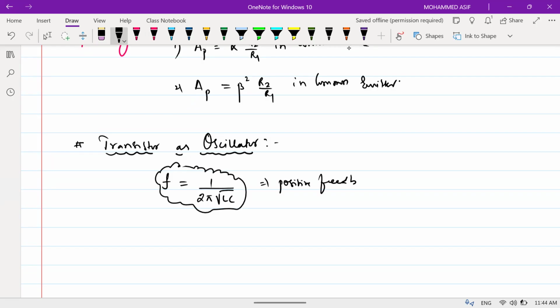Positive feedback circuit. For negative feedback circuit, better amplification is reducing the distortion. So positive feedback is used in oscillators, and negative feedback is used in amplification to reduce the distortion part of it. Clear? Am I clear, beta?